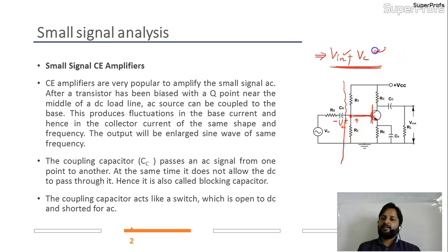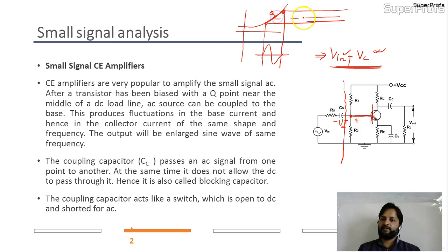Now because of this, your transistor is working in the linear region, or your transistor is moved into this linear region. Now you shifted your input. Let me take over here. Your input is like this. Here we'll get the output. Here is the Q point. Perfectly fine. Here we are getting output with proper shape. So at the output stage we are getting output over here. Is it okay? At the RC, at this level you are getting output.